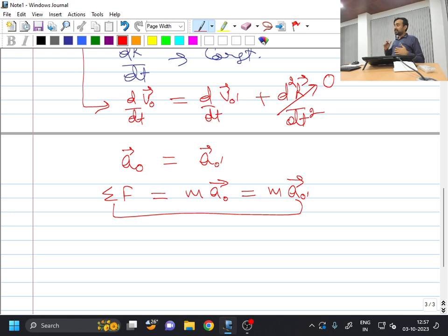velocity, and if with respect to that frame we are trying to trace a fluid particle, for that also our acceleration of the fluid particle will remain identical to that of the acceleration of a fluid particle measured with reference to a stationary frame. So that is the reason that both these two types of frames, the ones which are at rest and the others which are moving with the constant velocity, are considered as the inertial frames of reference, and Newton's law of motion is actually completely equally defined for both types of frames.